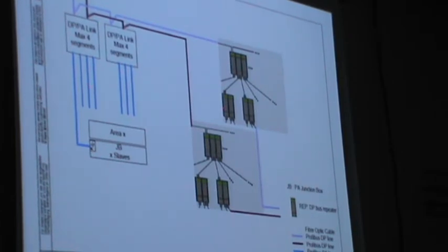So it will go to the different areas, and each will have an individual power hub to give the 24 volt power supply to your transmitter. This normally gives 24 to 30 volts because all these transmitters need only 24 to 30 volts to power on. But for flow, mag flows, we use an external power supply, as there is no other option.